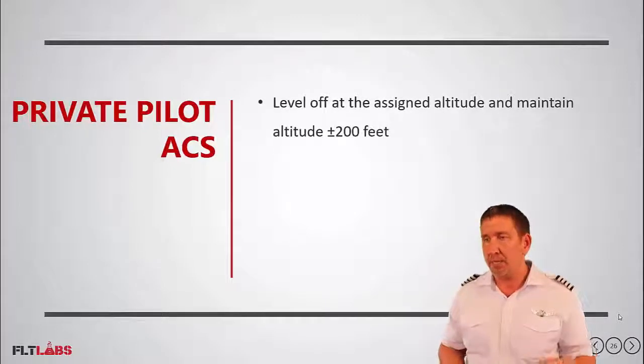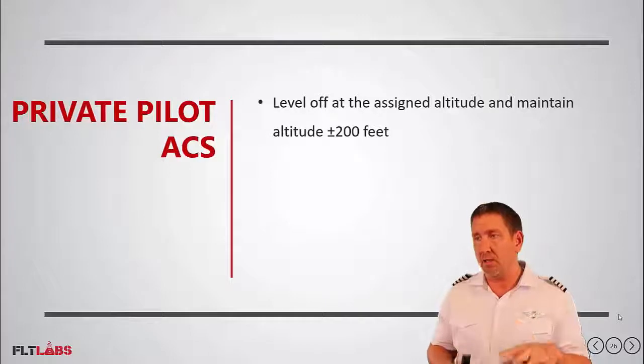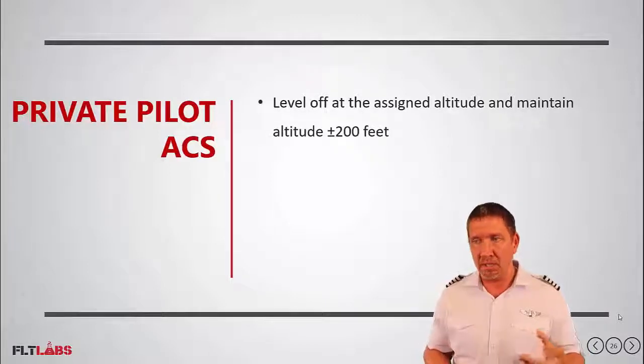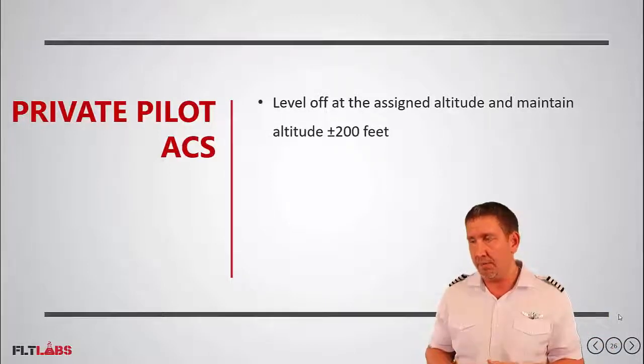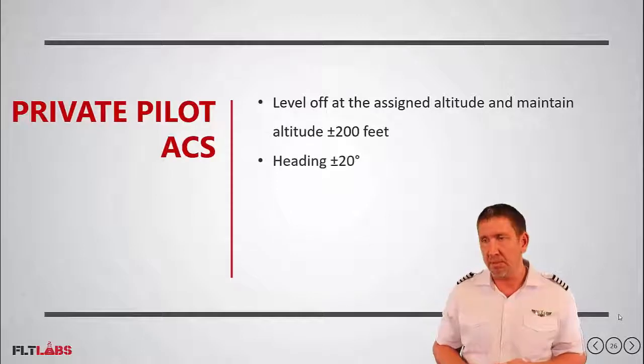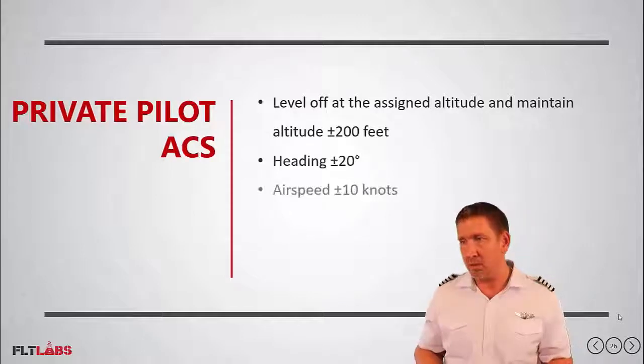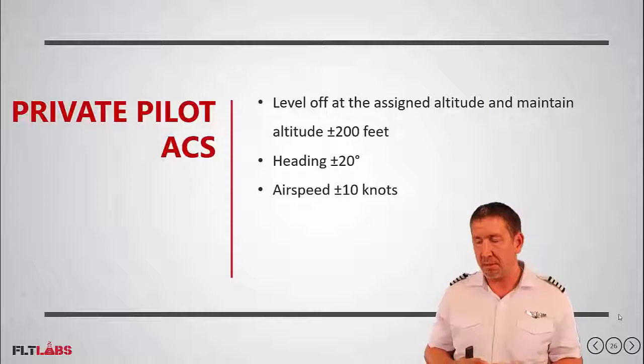What else do they say? They like us to level off at an assigned altitude and maintain our altitude within plus or minus 200 feet, heading plus or minus 20 degrees, airspeed plus or minus 10 knots.